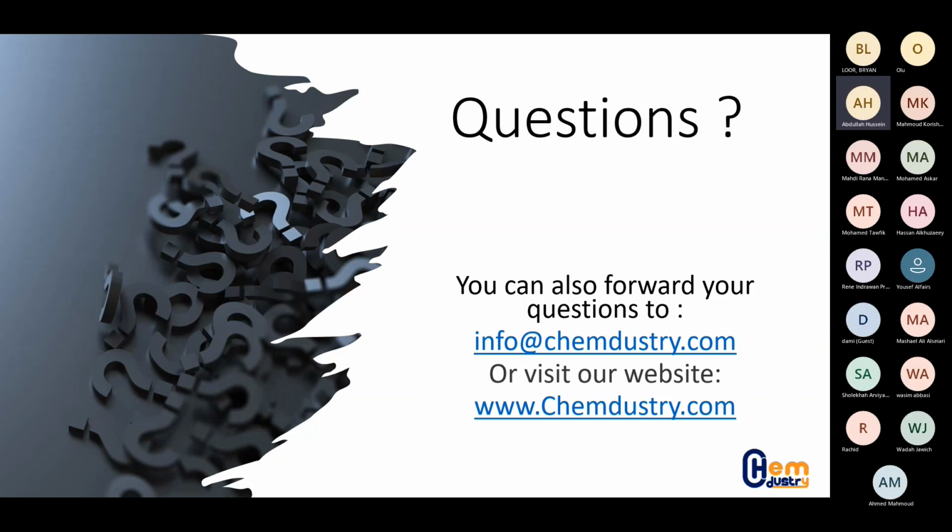After you do this, it is highly recommended if you can check on your well, especially if it's a well in a downhole, as you said. So check on this one and make sure that your well is actually in a good condition. If it's really old in service, let's say 15, 20 years, if the material is not really corrosion resistant, then you might need to do a checkup on your well down there before you inject the system.